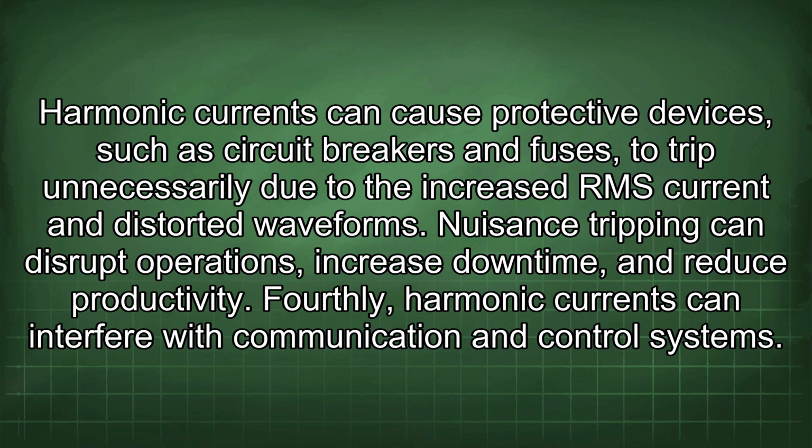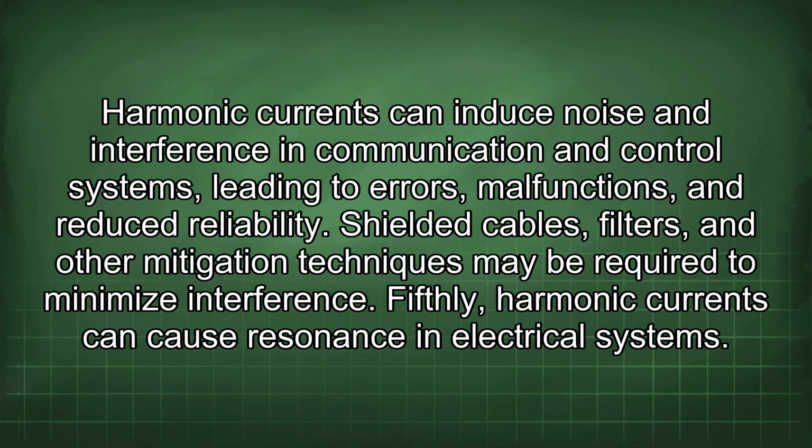Fourthly, harmonic currents can interfere with communication and control systems. Harmonic currents can induce noise and interference in communication and control systems, leading to errors, malfunctions, and reduced reliability. Shielded cables, filters, and other mitigation techniques may be required to minimize interference.